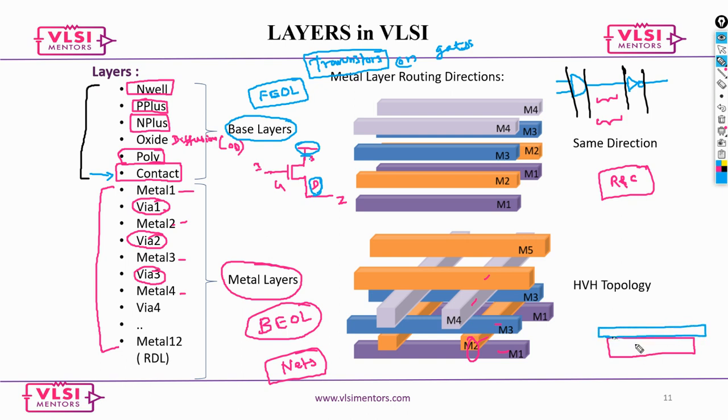Now let's say you want to connect these layers, say M1 and M2, which will have a layer doing like this. Before manufacturing this, you drill or etch. So now this brings something like this, so it's a via. Now when you do a metal deposition, metallization, it gets connected.